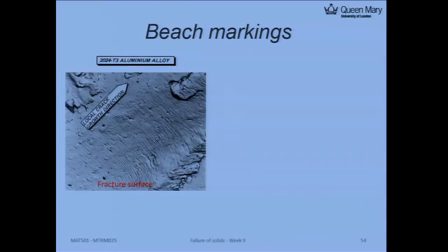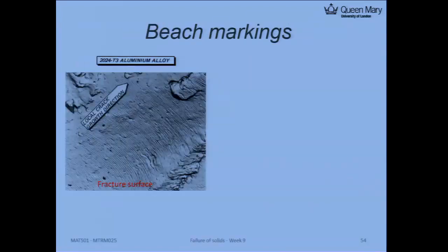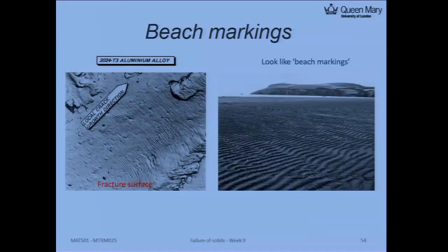on the surface. So if you look at some typical fracture surface of metal, now we are looking at the material from the top. From the top, you will see some wrinkling on the surface. We call it a beach marking. Like if you go to some beach, you will see some sand. We have a similar pattern like that. But this just gives you the visualized idea of this pattern. It's more like a beach marking.